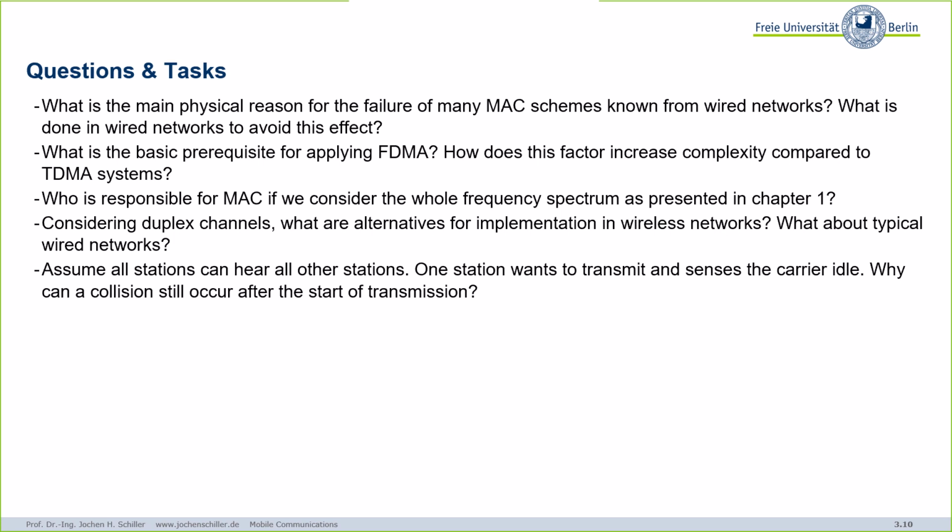And then the problem you have is in your so-called low noise amplifier. That's the hardware that actually receives the signal and amplifies it. You will not be able to detect anything from the received signal from the other side, because your own signal is that strong. It will simply drown out all the other signals. And that's the problem. Your own signal is 1,000,000 or 1,000,000,000 times stronger than the other signal.